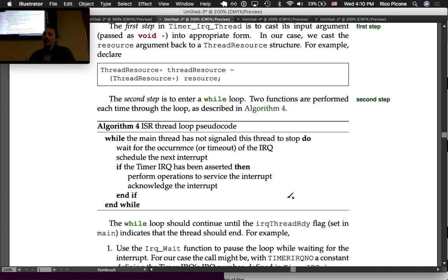You can't get ahead though. So if you throw the ball up in the air and you do something really quick and come back, you're going to get back on cadence because you're going to wait until that ball drops. You're not going to go grab the ball. You're going to wait till the ball drops each time. So you've got to wait each time. The one thing you've got to worry about is taking too much time in your ISR so that you don't overfill your time.